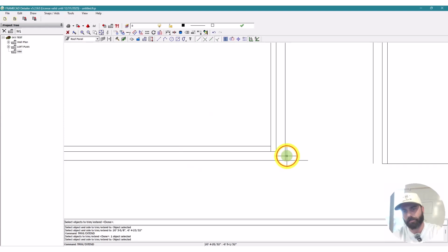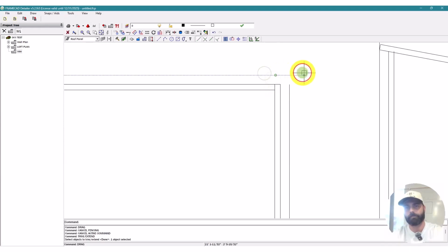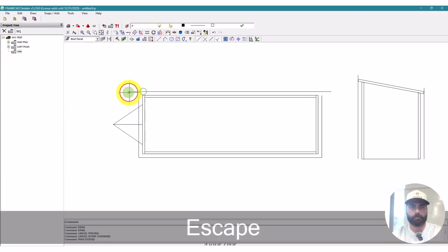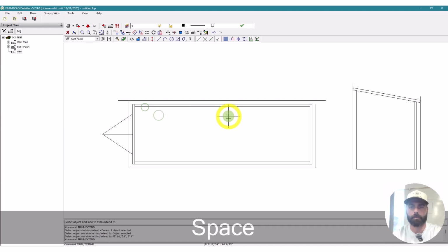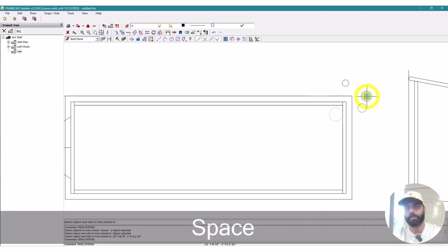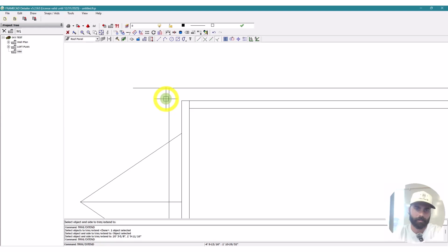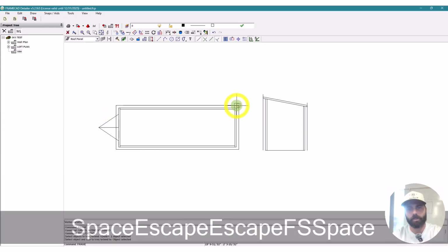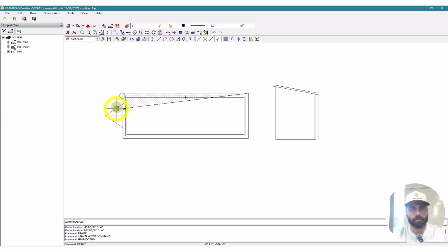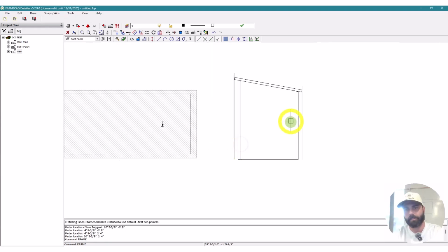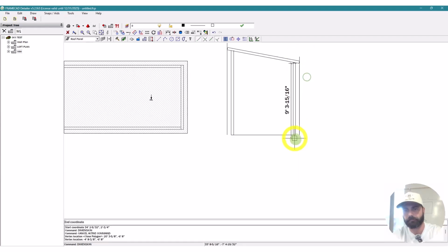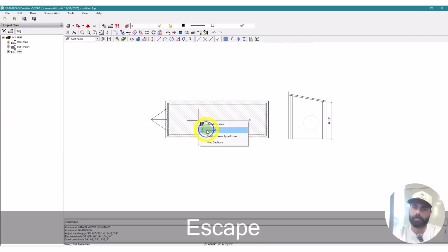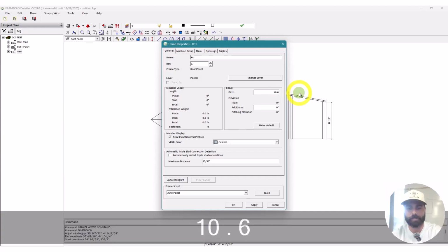Now this is another thing where we'll need one more dimension. So we'll do the same thing, draw that roof panel with 6 inches of overhang. And then I might potentially need this dimension here. So it's 8'11" off of the ground. 10.62 degree pitch. 8'11" off the ground, 16-inch stud spacing, 4-foot nogging. Let's go ahead and see how that looks.